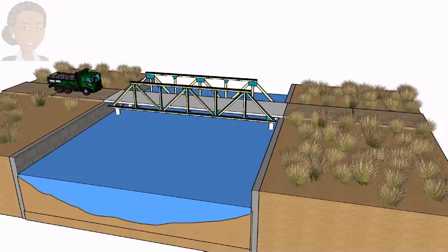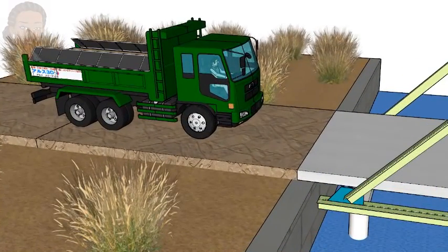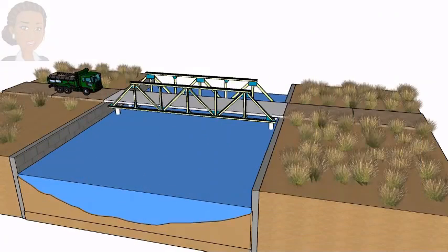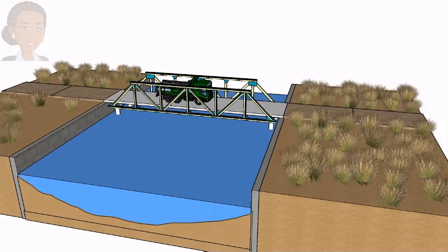The bridge is expected to support the maximum load of a truck having 3 axles. For the sake of our analysis, this can be viewed as a series of concentrated loads spaced according to the distance between the axles. So, we wish to determine the maximum impact that the moving load series could have on a given truss member. More specifically, we want to determine the truck location on the bridge that induces maximum axial compressive or tensile force in the member.